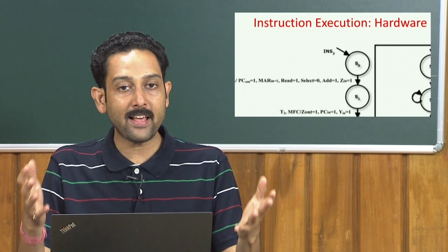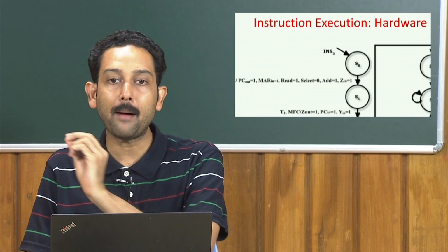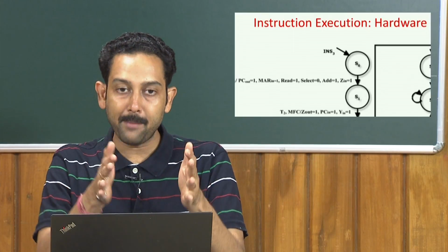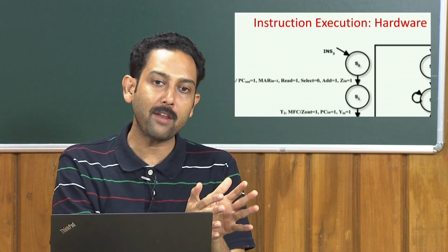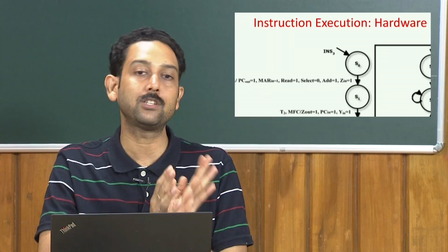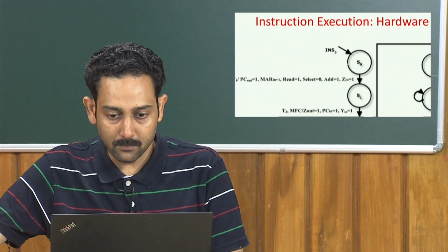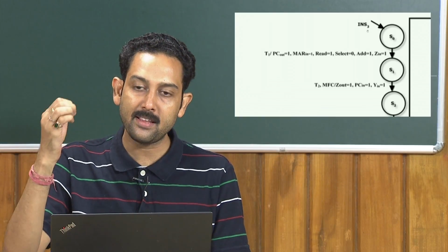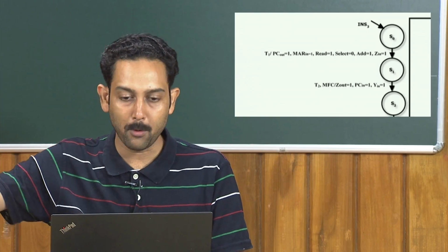So, if I have full flexibility, then it will become a program; this is your microprogram based controller, which we will see later. But for the time being we are giving dedicated hardware for each instruction, and it is the fastest way of implementation. So, in this case INS 3 is enabled, that means your instruction at present is jump on 0 to some location.